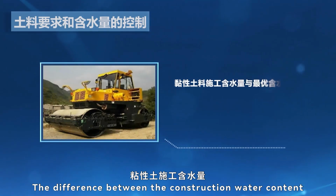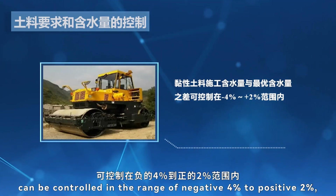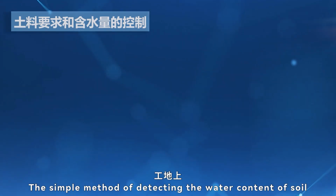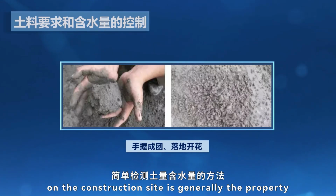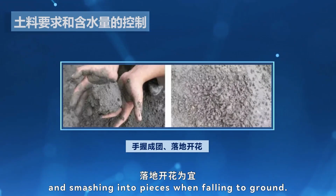The difference between the construction water content and the optimal water content of cohesive soil can be controlled in the range of -4% to +2%, and in the range of -6% to +2% when using vibration compression. The simple method of detecting the water content of soil on the construction site is generally the property of forming a lump when held in hand and smashing into pieces when falling to the ground.